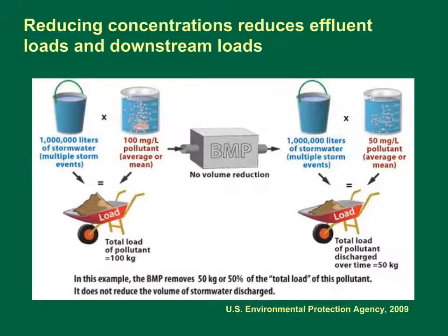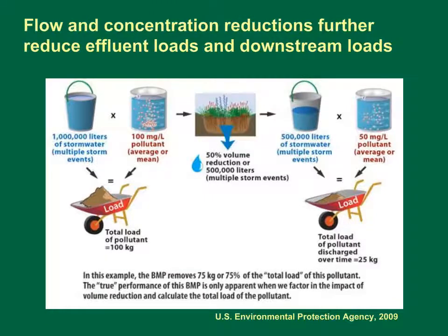Reducing concentrations reduces effluent and downstream loads. This cartoon from the US EPA indicates the potential effect of concentrations on discharge loads and therefore the potential effect on concentrations in receiving waters. This cartoon shows that if you cut the concentration in half without changing the runoff volume, then you cut the load in half. Flow and concentration reductions have a multiplicative effect to reduce effluent loads.